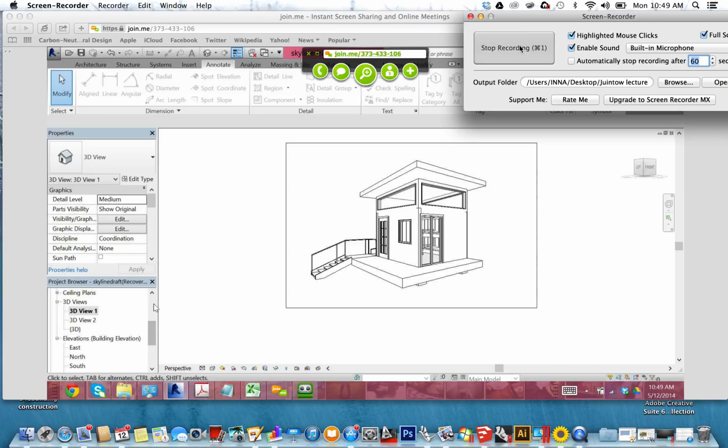Oh, so if we do T&G, one thing we could do is put the T&G on the top and then put the asphalt over that, in which case we could potentially reduce some of the materials, but then we have rafters coming out, and we'd have to enclose all the space between the rafters. So I feel like the T&G on the bottom is probably the best way to go.